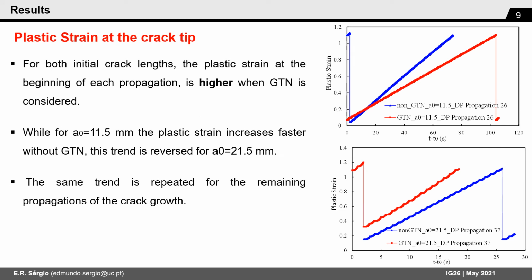In this slide, the plastic strain evolution is presented for both models for each initial crack length. The plastic strain is a cumulative entity, and it is presented here for an entire propagation. To assure that the results are comparable, the same propagations were studied in both models, corresponding to the stable propagation zone.